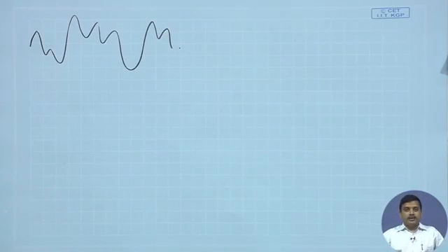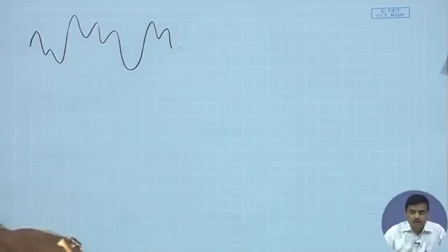What comes to your mind is through Fourier analysis you can break it down, and you can find the components of frequencies which build this signal. So there will be, let's say, a whole set of sinusoids, a huge number depending upon the bandwidth you restrict your system, and you find a coefficient for each sinusoid. So when you add them up with appropriate phase and amplitude, you can regenerate this particular signal. So what they studied initially is what is the response of a system to a particular set of sinusoids. So you would excite it by sinusoids, you will get the signal.